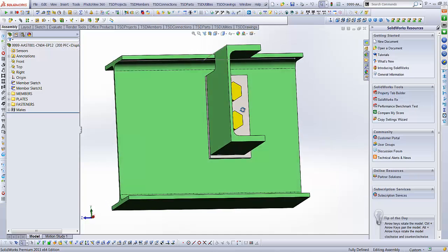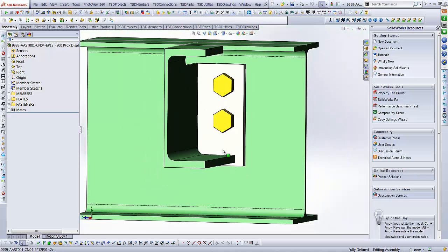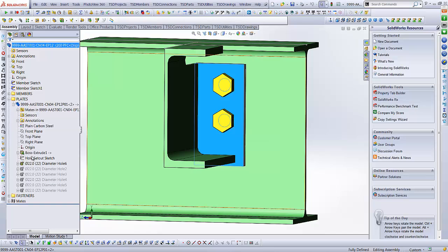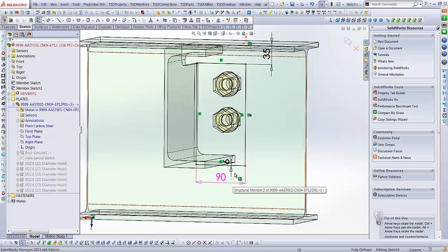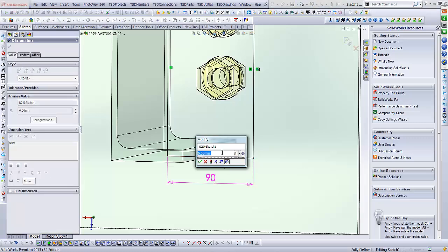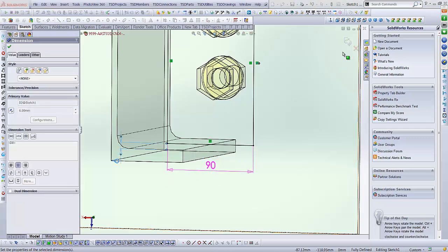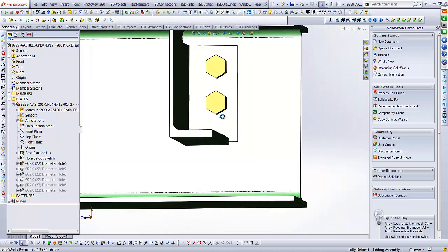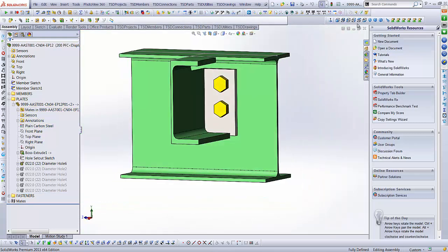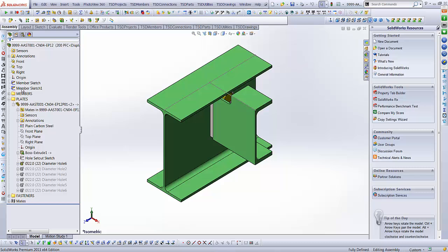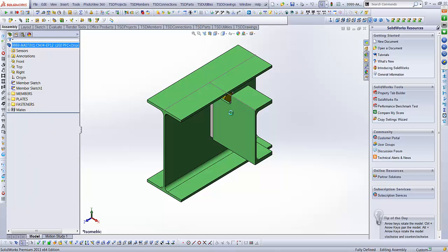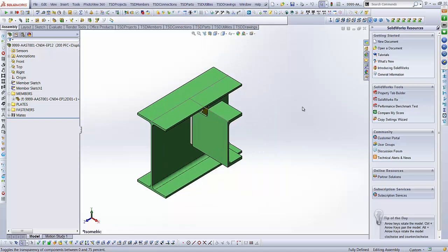And you'll also notice, and this is what SolidWorks happens to do sometimes, the set down that we did here for the 6mm needs a flip. So we've just flipped that, and that puts it back up so that we've still got our 6mm in there. Alright, so that's that one. Now remember, this is a dummy member, so you don't need to punch holes through it because it disappears anyway when we hide components. We'll show you that one in a later process, but for now I just wanted to show you how you create two connections.